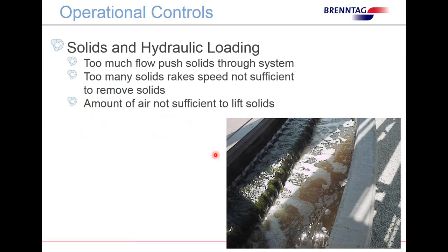Other operational concerns: too much flow pushing solids through the system. Clearly, at the slaughterhouse meat packer, that's what the problem was. Are there too many solids for the rake to keep up, and not enough solids removal through the system? And is the amount of air not significant to remove the amount of solids you have coming through the system?